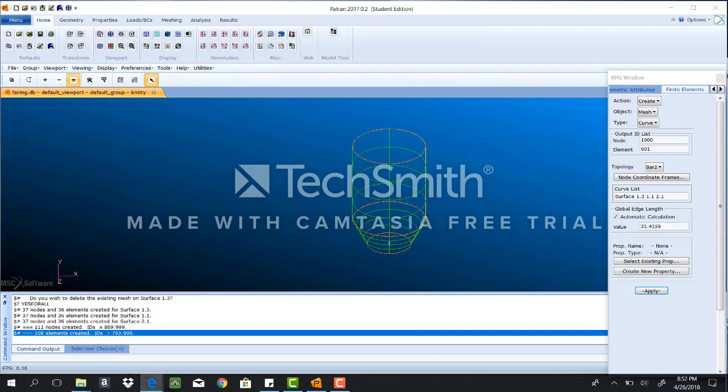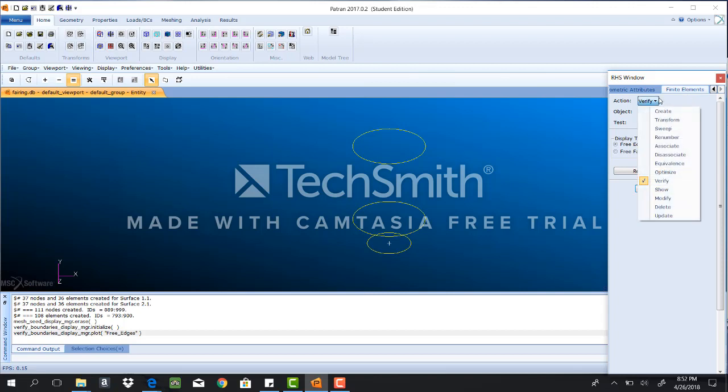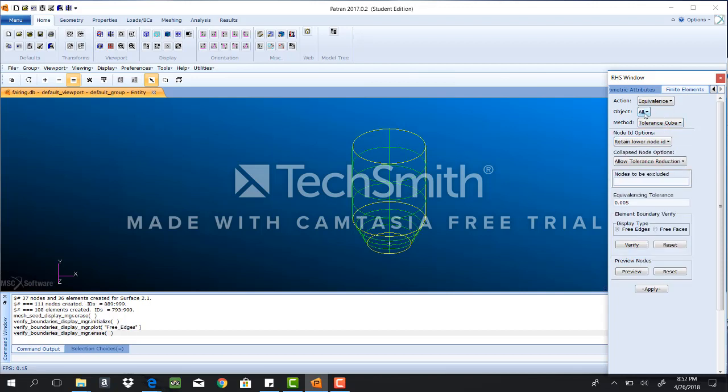After that, we're going to click nodes. We're going to verify element boundaries and then free edges and apply it. Well, now we go to equivalence, all, tolerance cube, and we click apply.